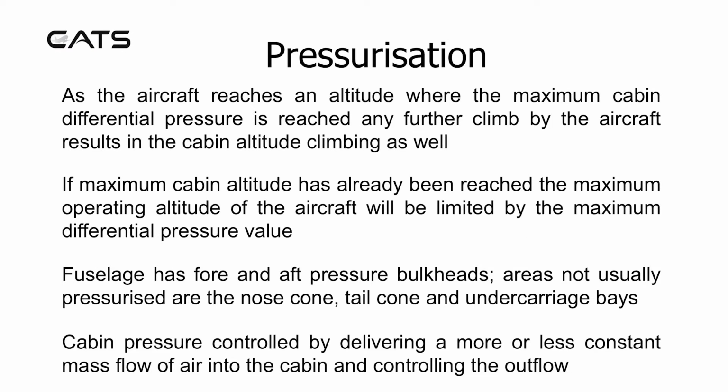As the aircraft reaches an altitude where the maximum cabin differential pressure is reached, any further climb by the aircraft results in the cabin altitude climbing as well. If the maximum cabin altitude has already been reached, the maximum operating altitude of the aircraft will be limited by the maximum differential pressure value.